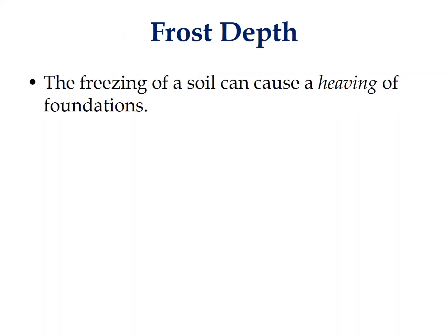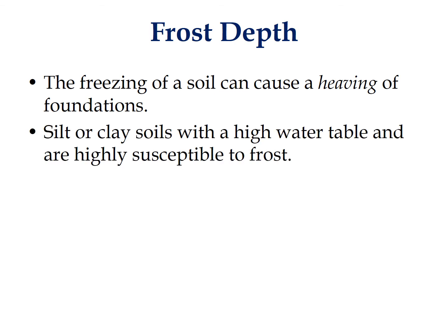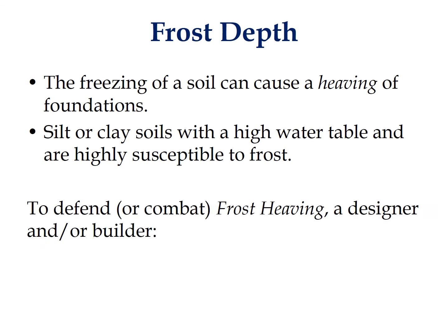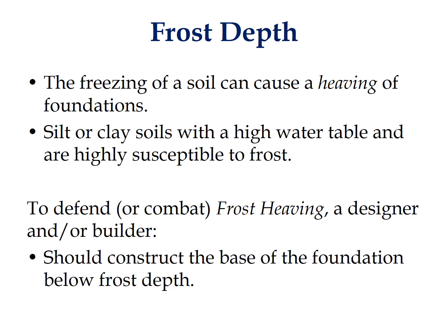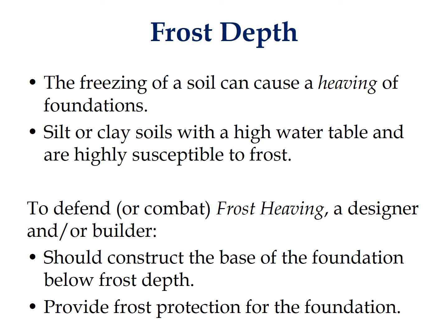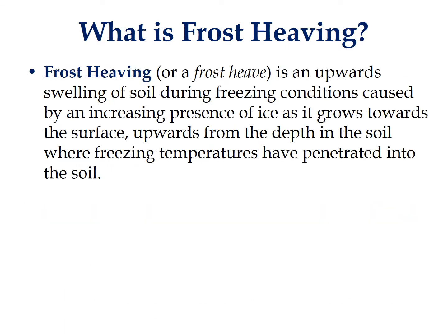The freezing of a soil can cause a heaving of foundations. Silt or clay soils have a high water table and are highly susceptible to frost. To defend or combat frost heaving, a designer or builder should construct the base of the foundation below frost depth and provide frost protection for the foundation.